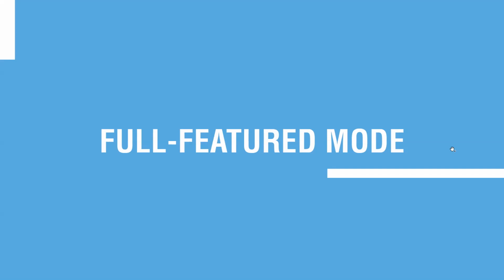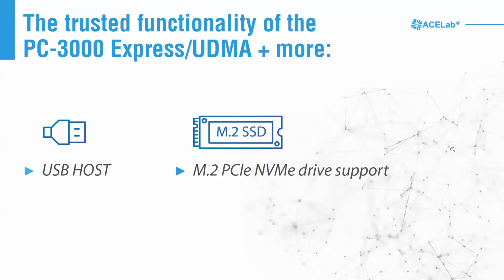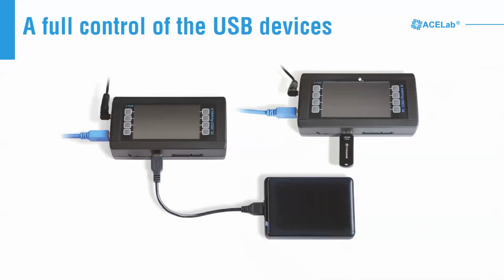So today, during the full feature mode demonstration, I'm going to show you how to work with the USB host port and how to work with an M.2 SSD drive. And first of all, let's talk about the USB host port. With the help of the USB host port, you can use USB sticks and native USB hard disk drives without the necessity to find a donor PCB, or to solder SATA onto the USB hard disk drive board. And actually, it might seriously help you with data recovery.